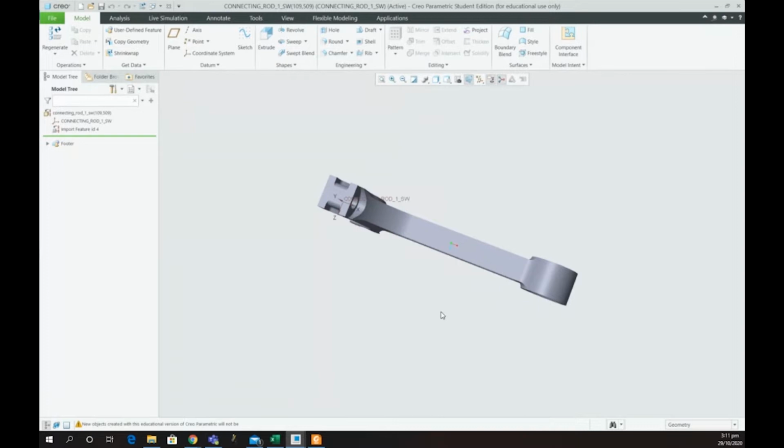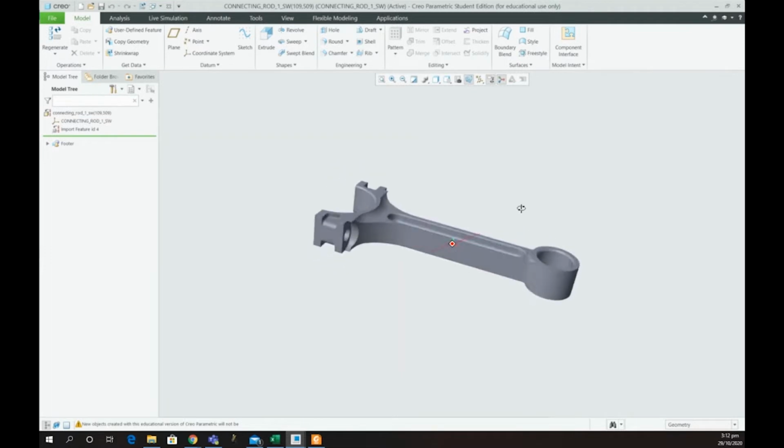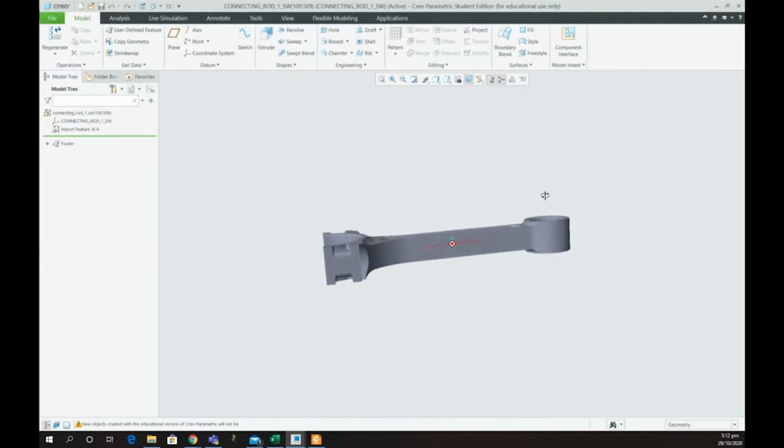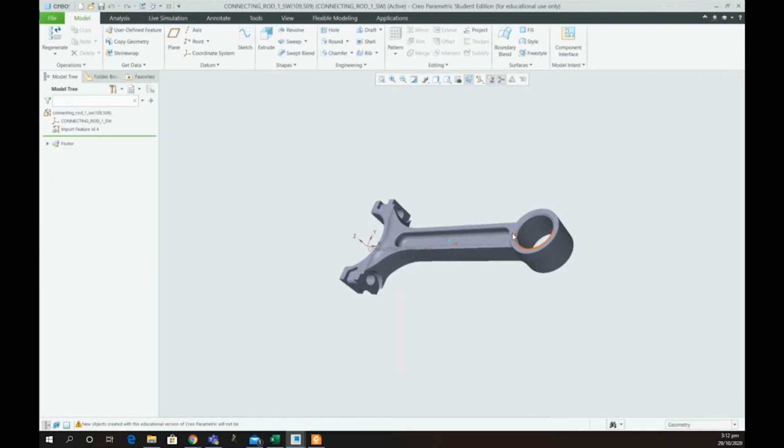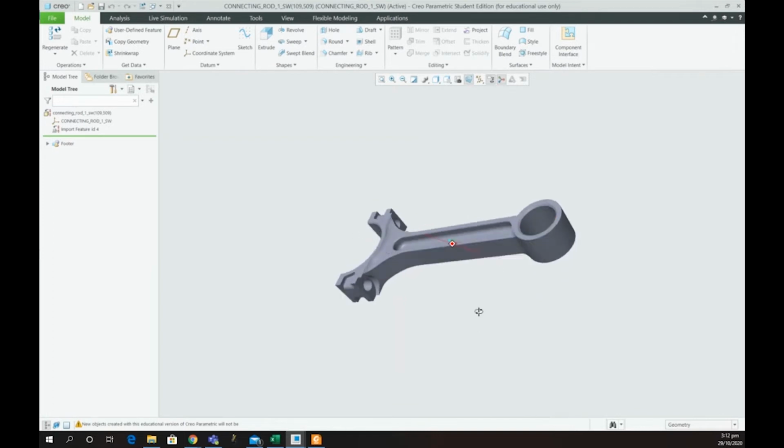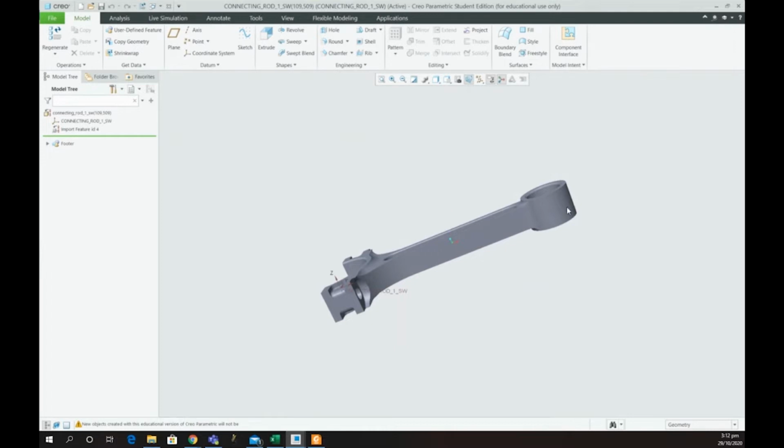So in my many years, I have seen some 2D drawings which are really bad. Just converting a thing into 2D and placing some dimensions is not enough. There are some rules which you need to follow. Some rules are such that Creo would not let you break them, and some rules you need to keep in mind. For example, no same dimension should be repeated twice in any of the views. You would see that more clearly when we are doing the drawings.